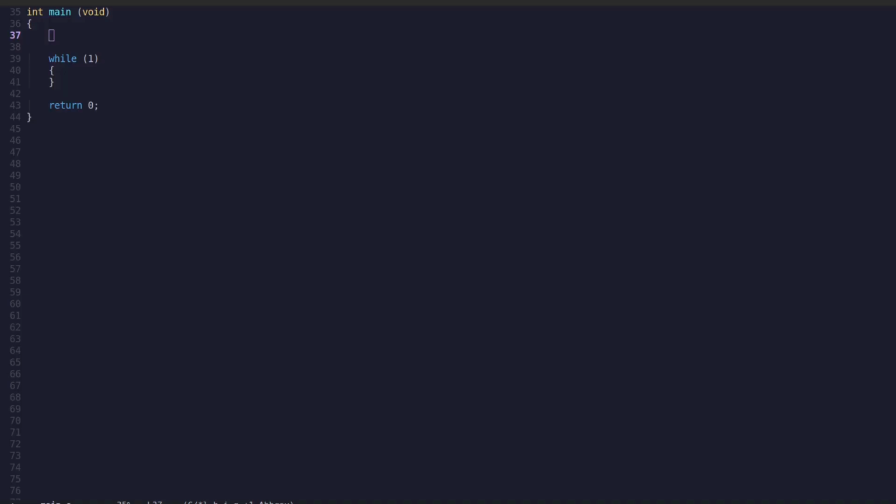Then we need to set this pin as alternate function, push-pull mode, and also to be able to use that port, we need to enable the clock for that peripheral. So these lines can do the job.